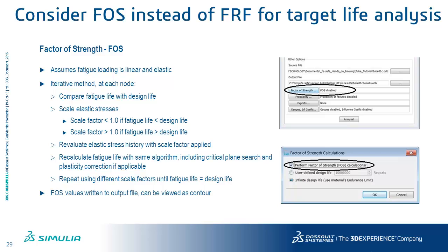You can assign that by using the output assignment, and then you can set up that FOS analysis with the analysis options, and then fe-safe will iteratively solve for those FOS values for you.